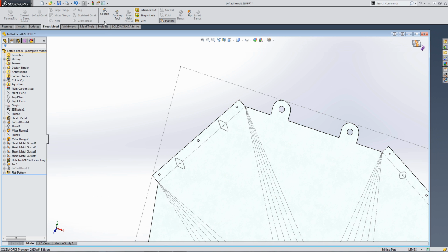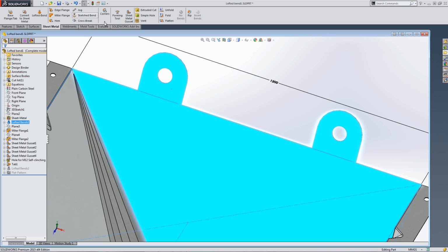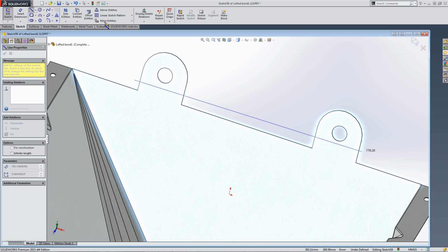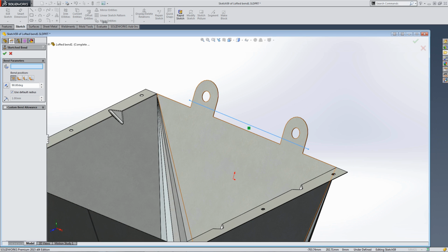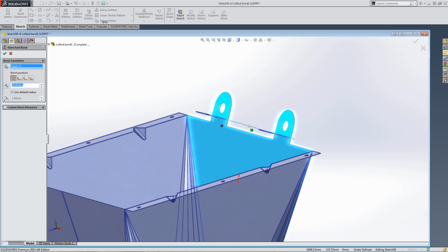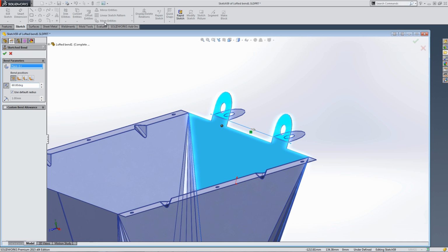That's pretty huge to me. Another nice enhancement in sheet metal is the ability to preview a sketched bend. So if I'm drawing a sketched bend, I can just say draw it through here. Just missed horizontal there. Draw it through there, and we'll say OK to that because I started it with the sketch bend. So now it goes to the sketch bend, and I can say what face is going to be fixed. And now I get a preview of it. So I can say, okay, I need to go 60 degrees, and I need to reverse the direction.